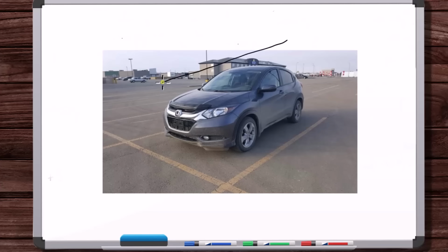All vehicles have a plane of symmetry down the center. The geometry of the vehicle is symmetric with respect to this center plane. Okay, but are the loads symmetric with respect to that center plane? Well, okay, we've got vertical force, let's say on the two back tires, but there's also, let's say, a traction force as well. And then we'll say this is not four-wheel drive, so there's no traction force on these tires, just a vertical force. You got the weight of the car at the center of gravity.